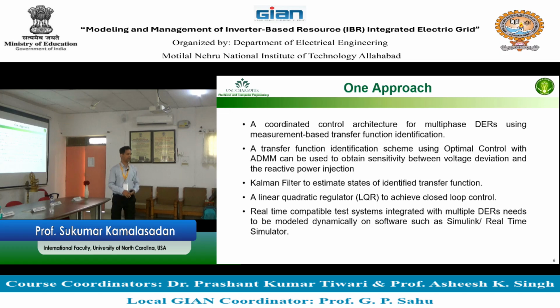Then you have what we call a tertiary level controller, which comes into the substation and the substation management related to that. So there are three levels of hierarchy in the management. What we are talking about today is not the local, device level control. Assuming that the inverter and the battery, or whatever is required, can take care of whatever set point we give, we are going to give that at the secondary level. How do we manage the secondary level coordination? That's the topic. Then we will slowly go inside the box and see how the box really works.